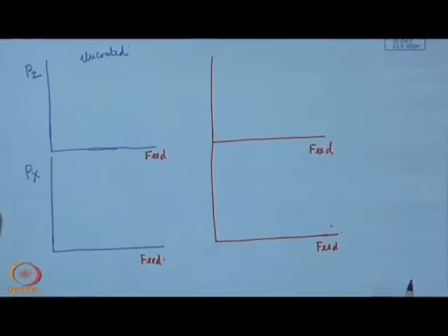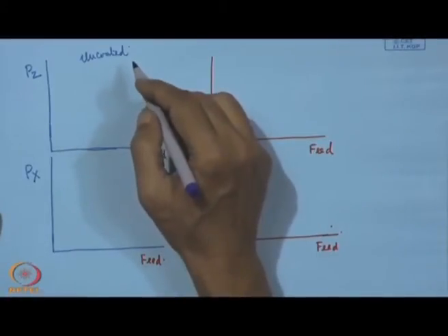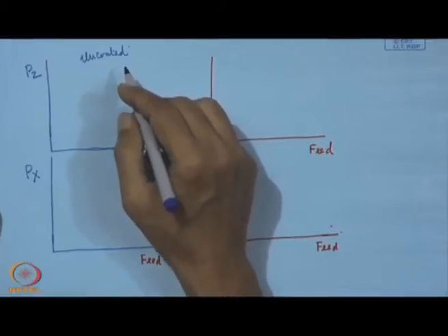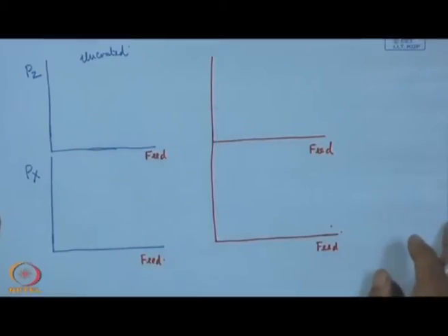Now, since HSS tools work in the low speed range, even with coating we can hardly cross 100 meter per minute. Normally, we restrict the speed limit for normal HSS to around 30. So, by putting a coating of titanium nitride, perhaps we can safely go to 60-70 meter per minute.